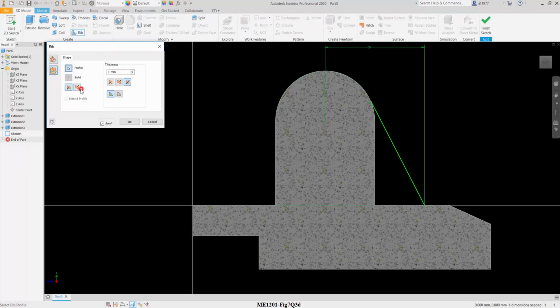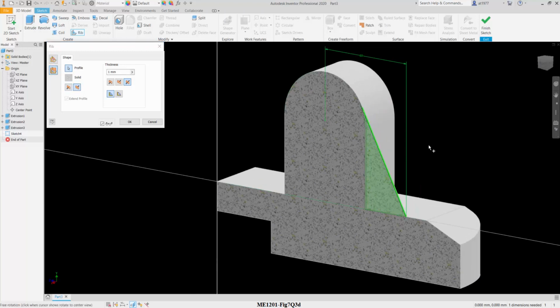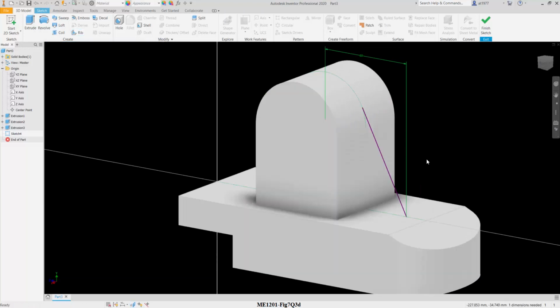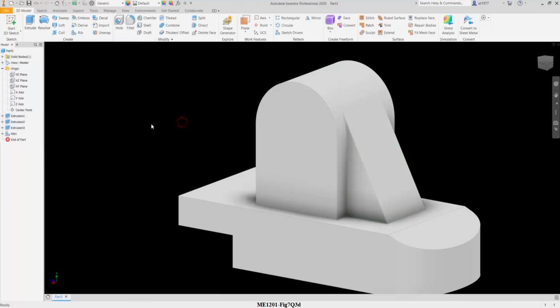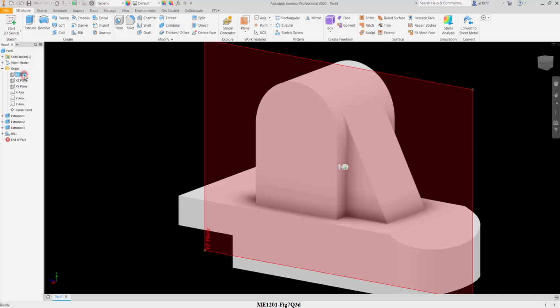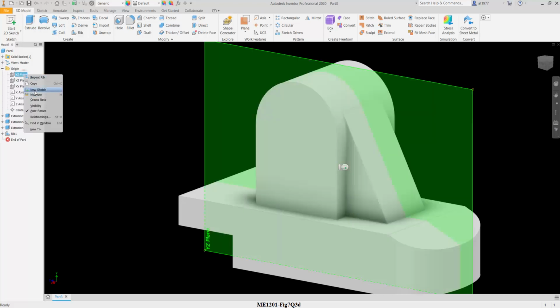Okay, change the direction. I can press F7 again, sorry. We can try this again. Okay, now the thickness should be 40 mid plane. Okay, next step, same thing again, we can make use of the YZ plane to create a cutout in the middle.